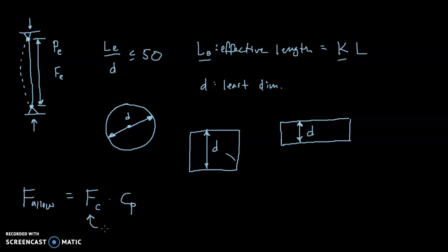This comes from the appendix. It is the allowable stress in compression, that's what the C comes from, parallel to the grain. And that's how timber beams are arranged. We've got, not beams, columns. A timber column runs the same length as the trunk of the tree, so the grains of the wood are running vertically. So when we apply a load to a column, that load is running parallel to the grain.